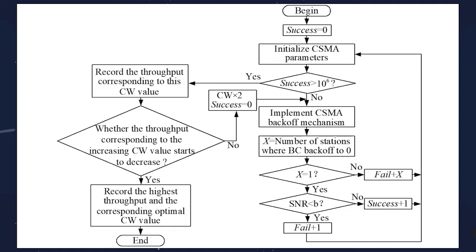According to these two parameters and the transmission power, the signal-to-noise ratio expression is constructed, and it will be compared with the threshold. If the signal-to-noise ratio of the signal is lower than the threshold, the channel will be interrupted and the packet transmission fails. Otherwise, the packet will be transmitted successfully, and the successes and failures will be counted according to the success or failure of the transmission.